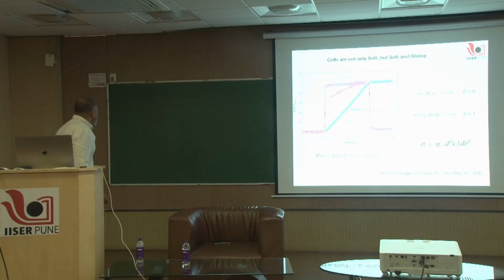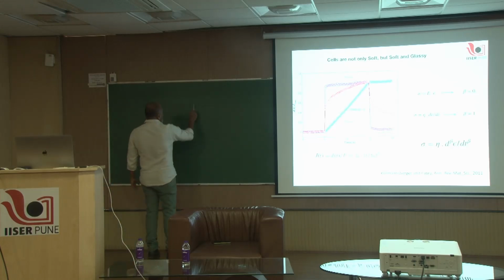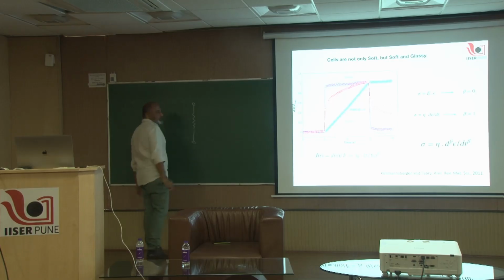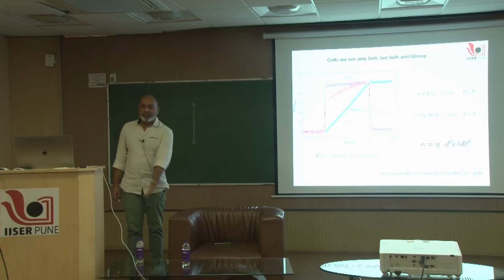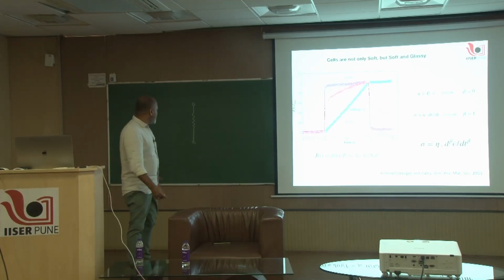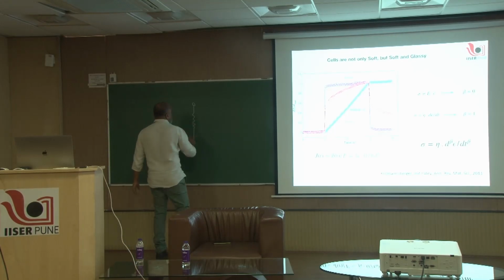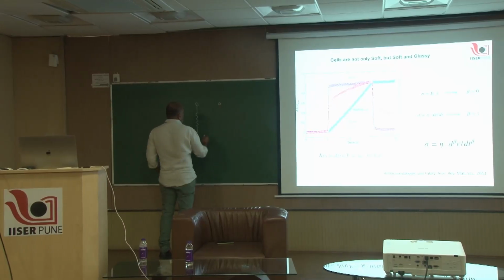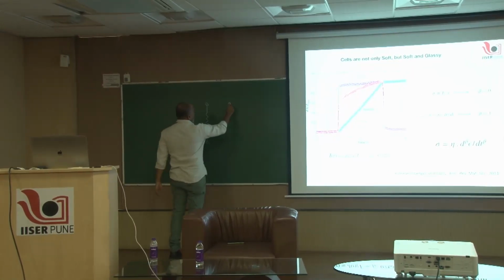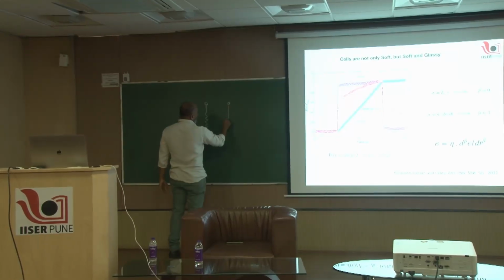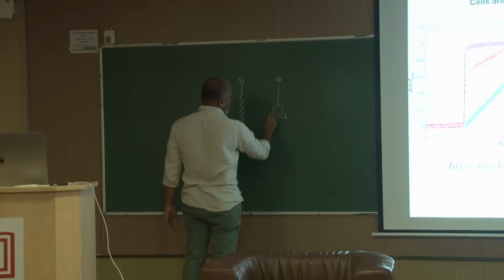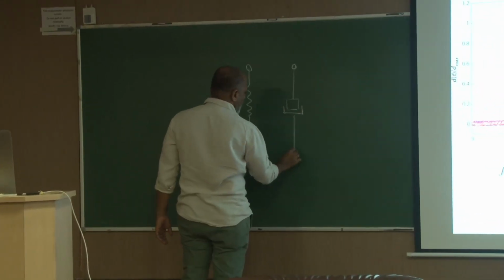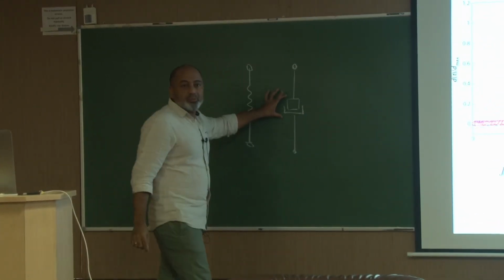So elastic solids, one can describe them as a spring, like we think about circuit elements, resistor, capacitor, inductance, all of this is described in such a way. So this is a spring, where the force and extension are proportional to each other, and there is also this dashpot to describe the viscous part in the material.